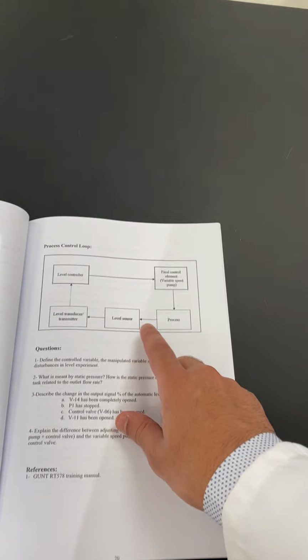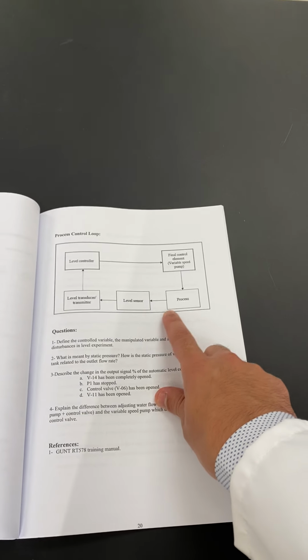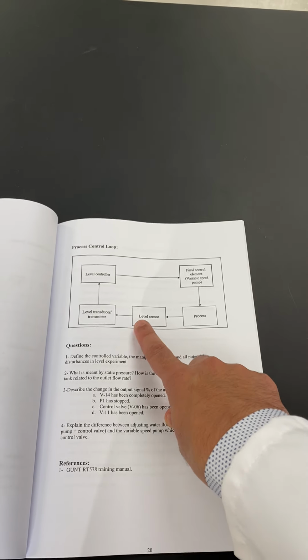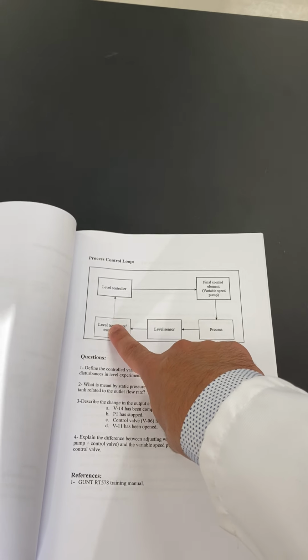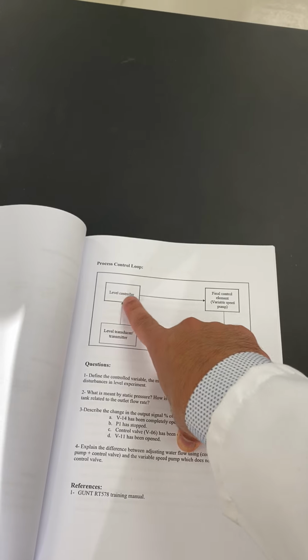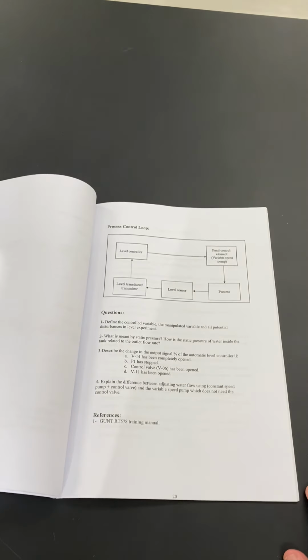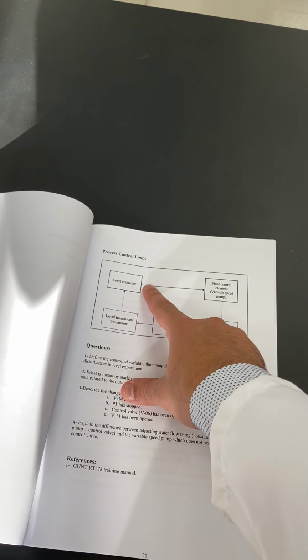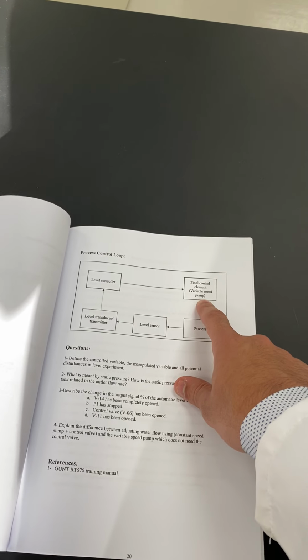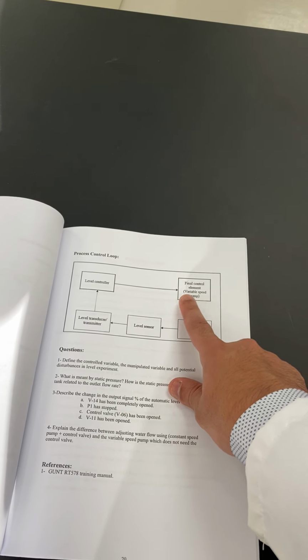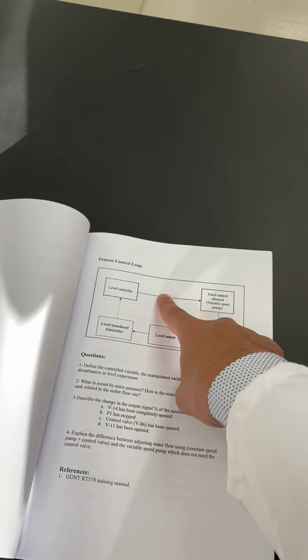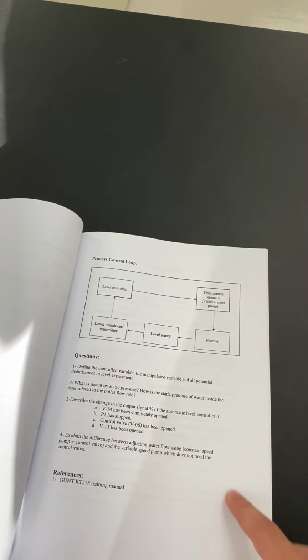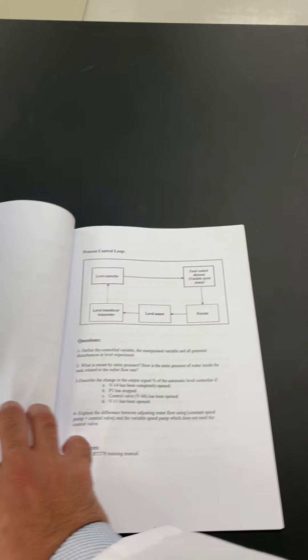As you can see right here, guys, we have this process, our tank, we have a level sensor, transducer, transmitter, then the signal is transmitted to the controller, and as we said, a comparison between the measured value and the set point will determine the output signal from the controller to the final control element or the actuator, which is our variable speed pump. We don't have an I to P converter in between because it is electrically operated. So let's have a look at